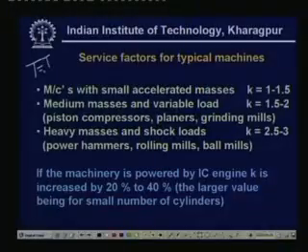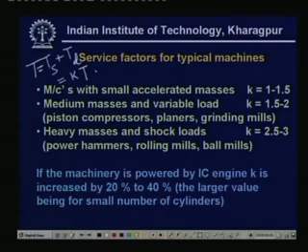because the shafts are used to drive various machines. So, there will definitely be some fluctuations of the torque. So, the total torque will be equal to T fixed torque, that is the static torque, plus T dynamic torque. So, this T dynamic torque varies from machine to machine, and we have to take this as a factor on the static torque. So, whenever we have a static torque, that is fairly known, then we have to multiply by this factor. And how to derive this factor? Again, these are derived only from the previous experience. So, this is known as the service factor.